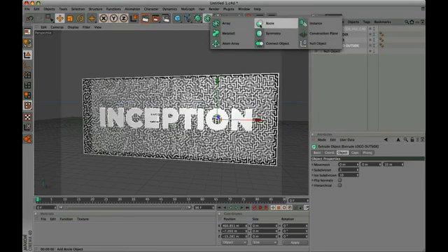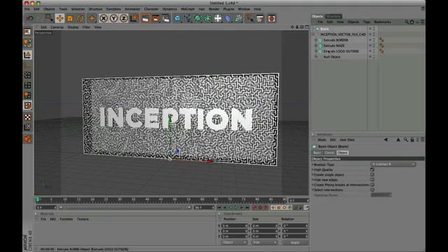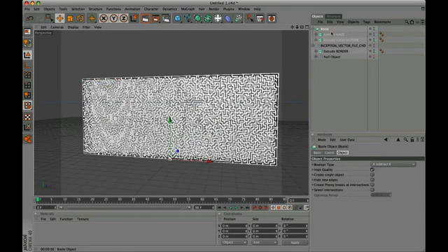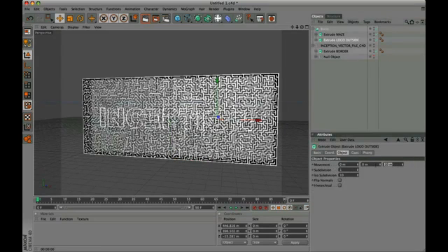Insert the Boolean tool, and drag on it Extrude Maze and Extrude Logo Outside. We apply the type Boolean A without B. Increase the extrude depth from 10 to 20 to get the result.